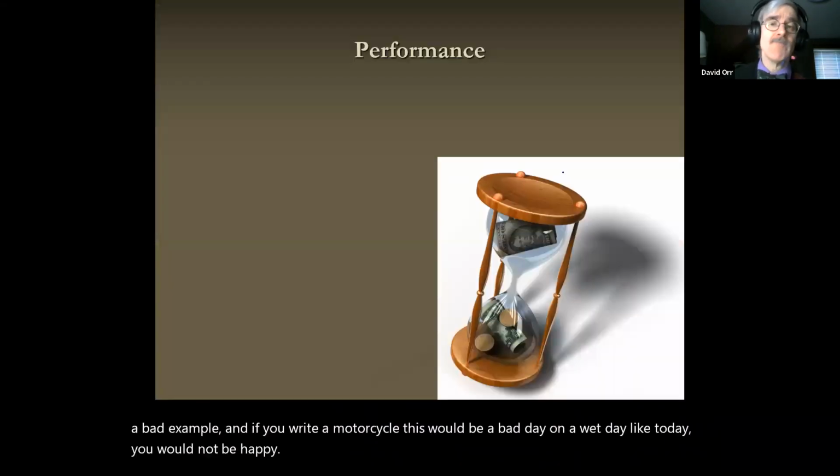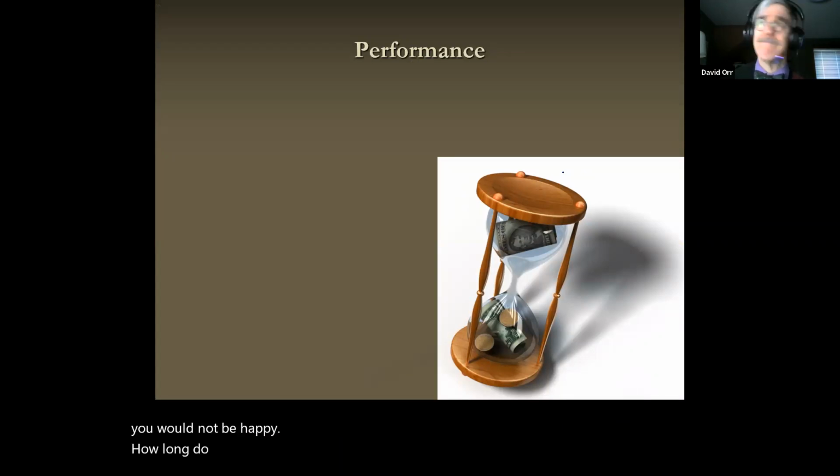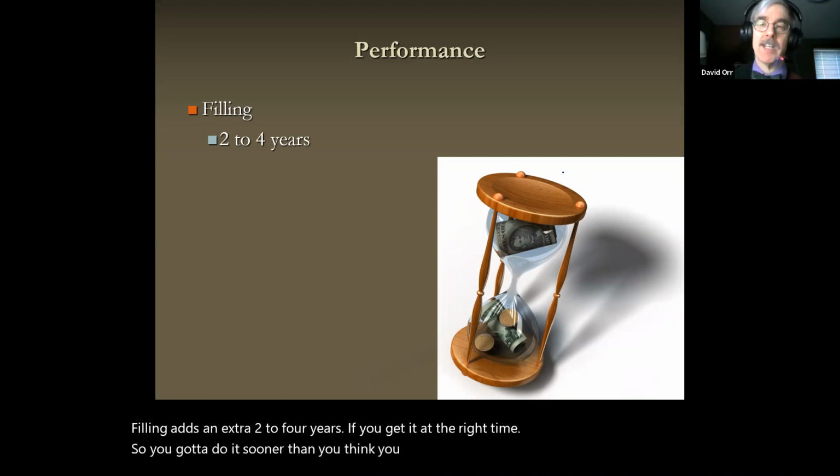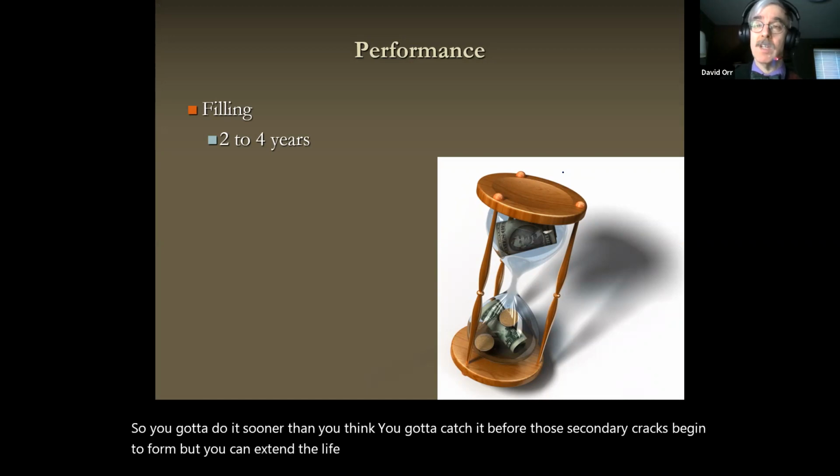Okay. Now, how long do these things last? Well, filling adds an extra 2 to 4 years if you get it at the right time. So you got to do it sooner than you think. You got to catch it before those secondary cracks begin to form. But you can extend the life of the surface before you have to do a recycling or an overlay or even a rehab by 2 to 4 years. That's cheap.